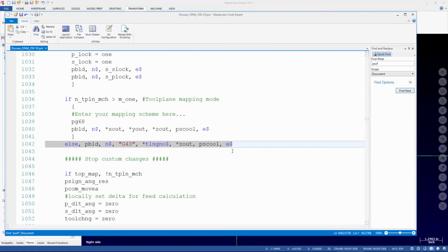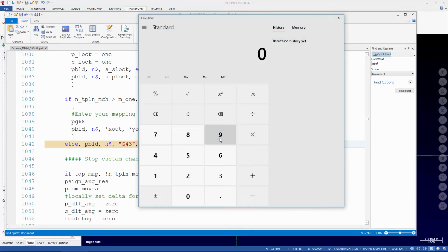I like Jeremy's comment, run it till it stops. Yeah, and same thing with negative. Give it a negative 720. The other thing you can do is program a large revolution. So tell it to do 50 revolutions. You're going to be at rapid, so it's going to sit there for a while. But if you do 50 times 360, program C 1800 and see what happens, or C negative 1800. And watch out for overheating. That's a good thing to be aware of.